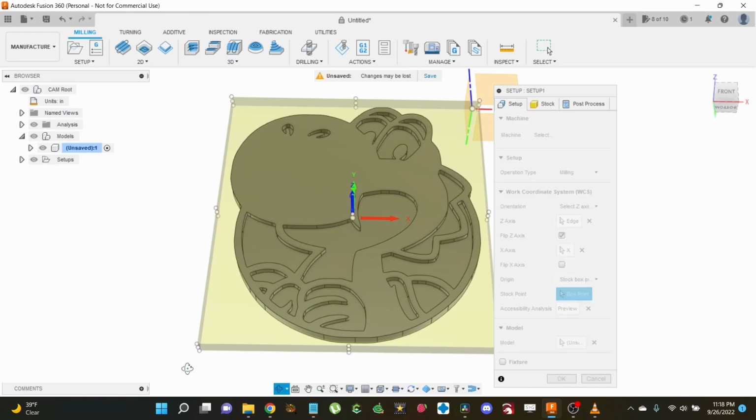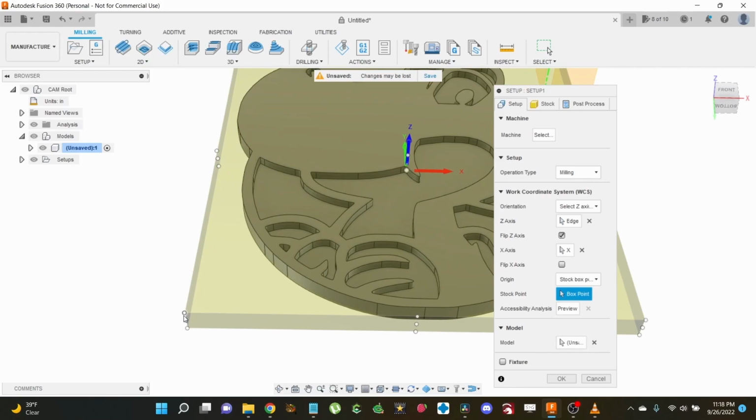The big choice here is to zero from the top or bottom of that corner. My advice, if you are only planning on cutting pockets from the top, then zero from the top. However, if you're going to cut out the project down to the spoil board, zero from the bottom, and your spoil board will thank you.